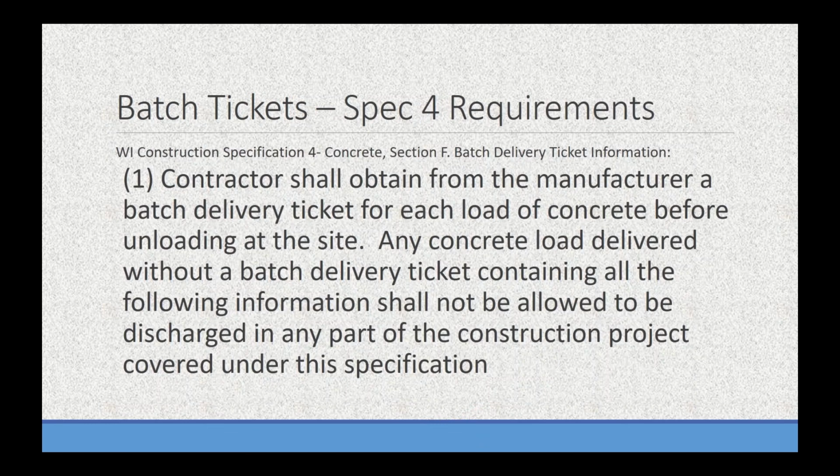So what are those requirements? Let's dive into what they are. If you've got Spec 4 in front of you, this is in section F on page 5. So the contractor shall obtain from the manufacturer a batch delivery ticket for each load of concrete before unloading at the site. So this makes sense.